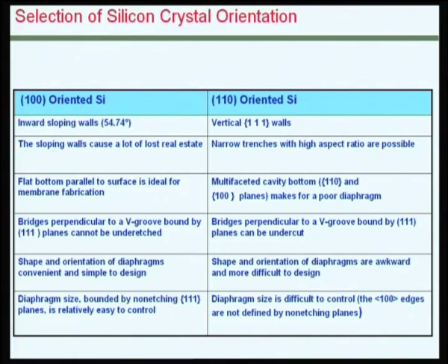We can get a nearly flat surface on the bottom floor after etching in 100. The multifaceted nature of the 2 opposite sides in 110 can cause floors which are not parallel to the top surface when etched using 110 wafers.